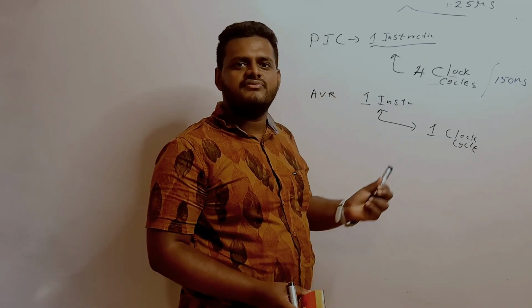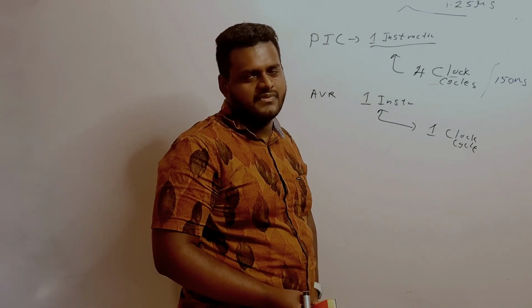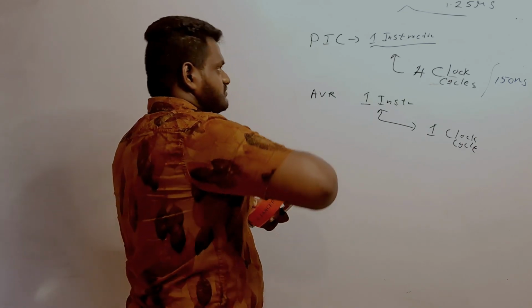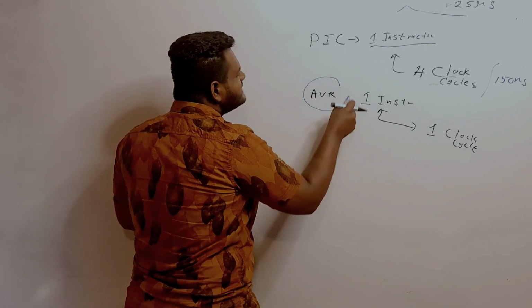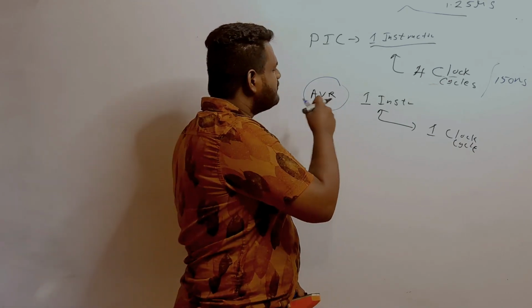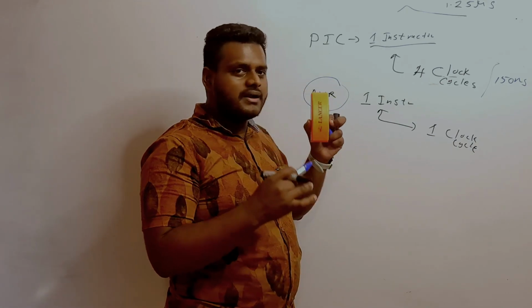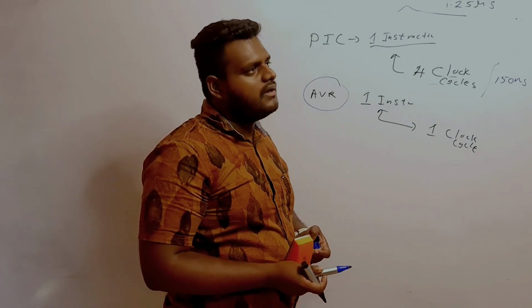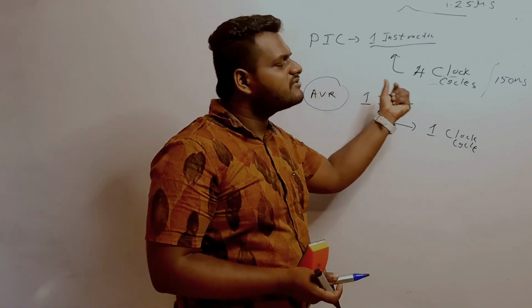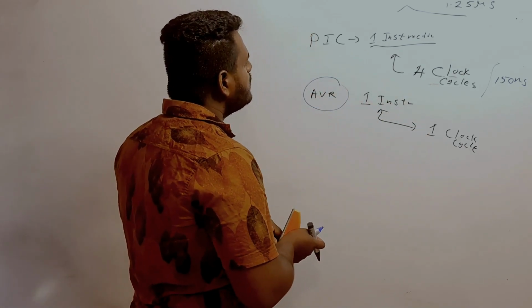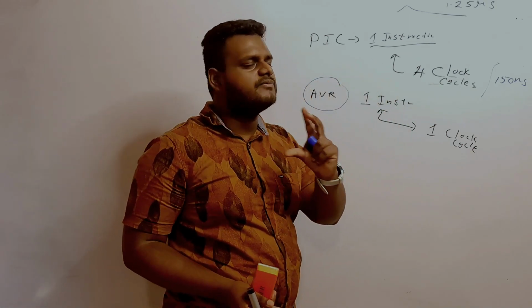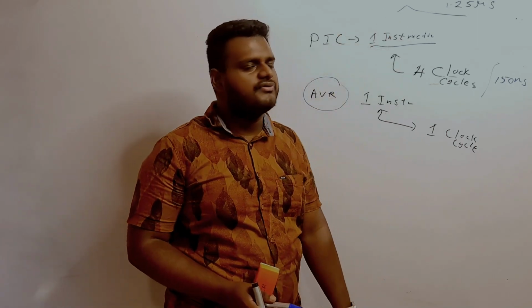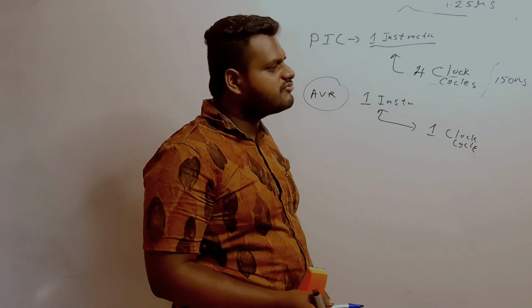You can run one instruction much faster. So with this facility, you choose AVR as one of the best options to run this, using AVR. So no, this is not actually the problem. Let's consider how many clocks we need to run this 125 microsecond timing data stream.